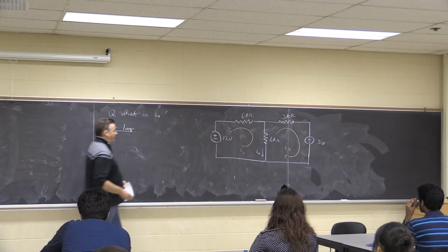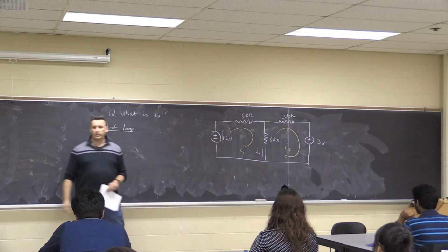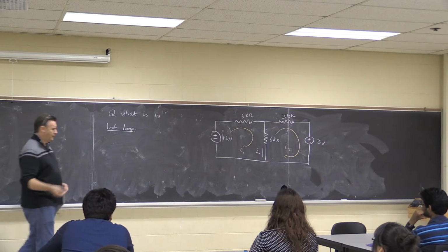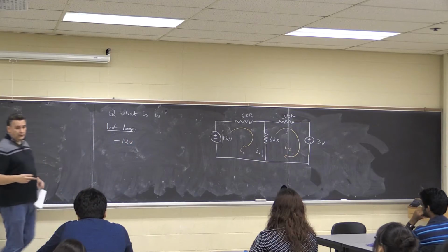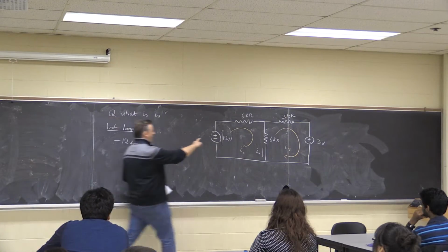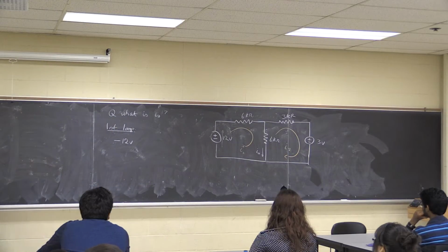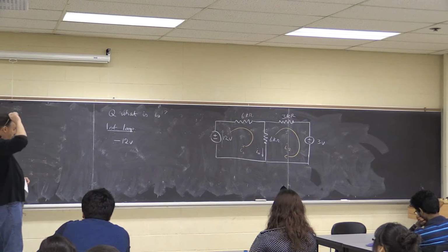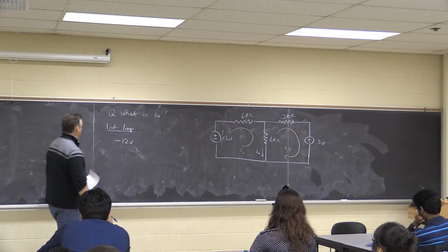The book basically makes a convention that if I go through a voltage source from negative to positive, going from the bottom line through this, I'll call that a negative voltage. I'll say I've got negative 12 volts. If I do that, the voltage drops must be positive. So the voltage drop due to the current flowing through this resistor must be positive, and the voltage drop going through the next resistor must be positive. And that's exactly saying voltage drops on one side, voltage increases on the other side. So whichever makes sense to you, I'm happy if you want to work with.